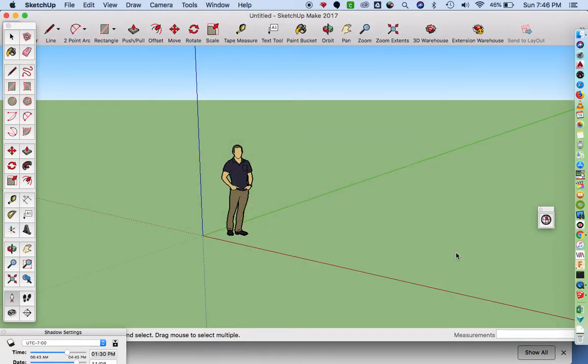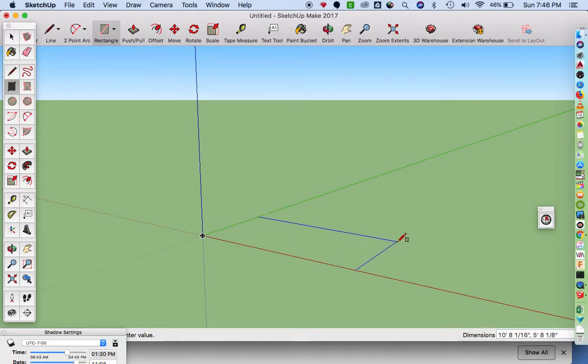So I'm going to come over here to SketchUp. The first thing I'm going to do is create the shape with the rectangle tool. I'm going to click, drag, and type in the dimension. I'm going to do a width of 4 inches, 4 quotation, comma, then the depth is 1.5 inches. So I'm going to say return.